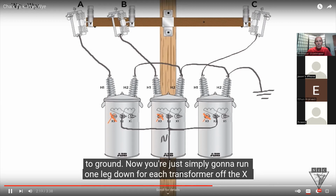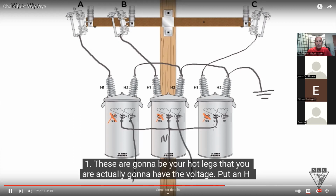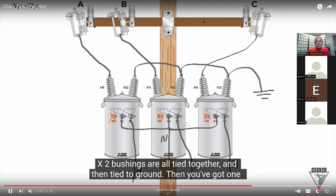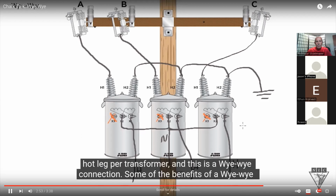Now you're just going to run one leg down for each transformer off the X1, and these are your hot legs that actually have the voltage. Put an H by them since they're each hot legs. So that's a secondary connection on a YY. X2 bushings are all tied together and then tied to ground, and then you've got one hot leg per transformer. And this is a YY connection.